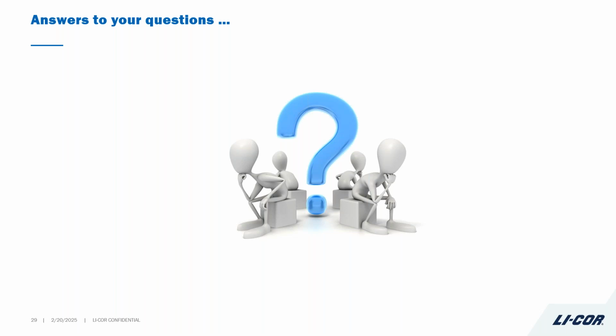Those can be based on measurement levels, so maybe when the water level gets to a certain level, you want to get notified, or it can be system issues. For example, if the station solar panel got knocked off and suddenly it's not recharging, if you get a low battery, you can get what's called a system alert to tell you that, hey, your battery level's going down too low, and you can go out and service it before you lose data. So those are important as well.